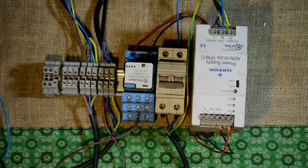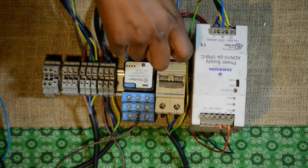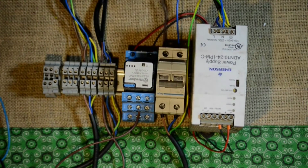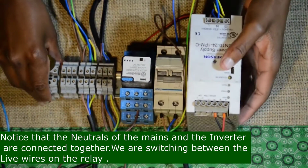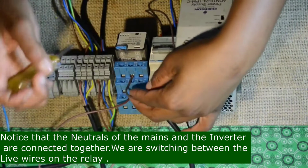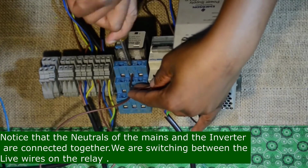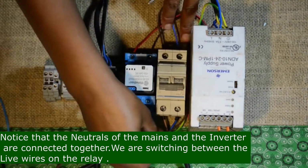So now that I've run my live through the circuit breaker, I can now take it to the relay where it can be switched. So this one basically is gonna go to the normally closed. So what this means is that when there is no power, this circuit will come on. Normally closed means that in the absence of power, if it's not on, it will be closed, right? And so it will close in between the load and the inverter.